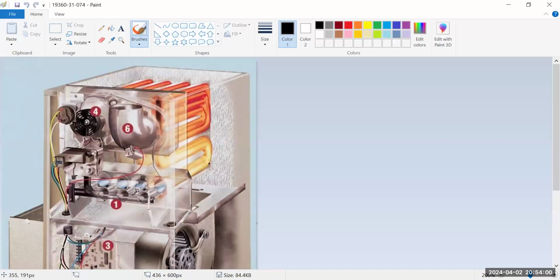That's going to make your flame move around. But what's worse is the carbon monoxide in the heat exchanger is going to leak out into your furnace and then into your ductwork. Now you're dumping carbon monoxide into the house every time you run the furnace. So we definitely do not want a cracked heat exchanger, because then you're going to go nighty-night and not wake up again.